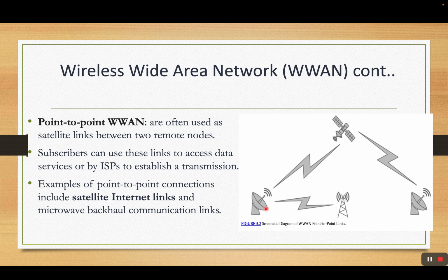The communication satellites used for commercial point-to-point internet connectivity normally operate in the Ka and Ku bands with microwave signals. The microwave frequency used for the Ku band, for example, is 12 to 18 gigahertz. The frequency range for the Ka band microwave is 26.5 to 40 gigahertz.